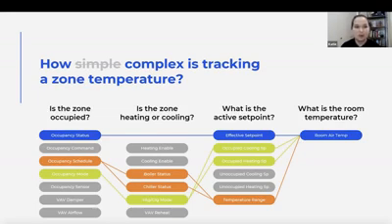So this is an important thing to ask your providers about: maintenance of the fault. What is your fault detection and diagnostics program going to look like on day 1? And what is it going to look like on day 100? And how long is it going to take you to get there, right? So if you have to customize each one of your faults all over campus, it's going to take you a really long time before you have actionable information. And then if something were to change, how does that change management happen? How long does it take? That's an important nuance.